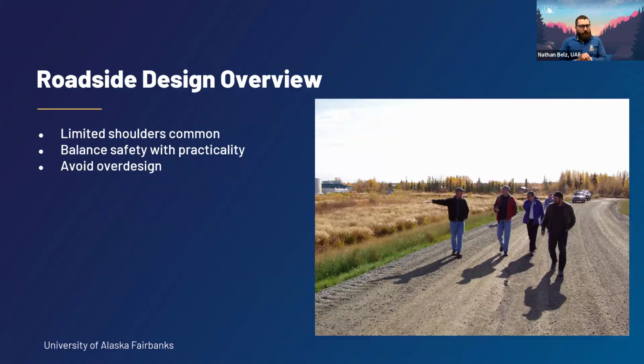In terms of roadside design, we're now talking about the area next to the travelway, not the travelway itself. In many cases, and in many design philosophies, this area is crucial for safety if a vehicle were to leave the road. Oftentimes, in villages, it's not practical, or one is not able to provide shoulders because of either the topography, obstructions, or right-of-way issues. So making these wider roads might not be achievable.